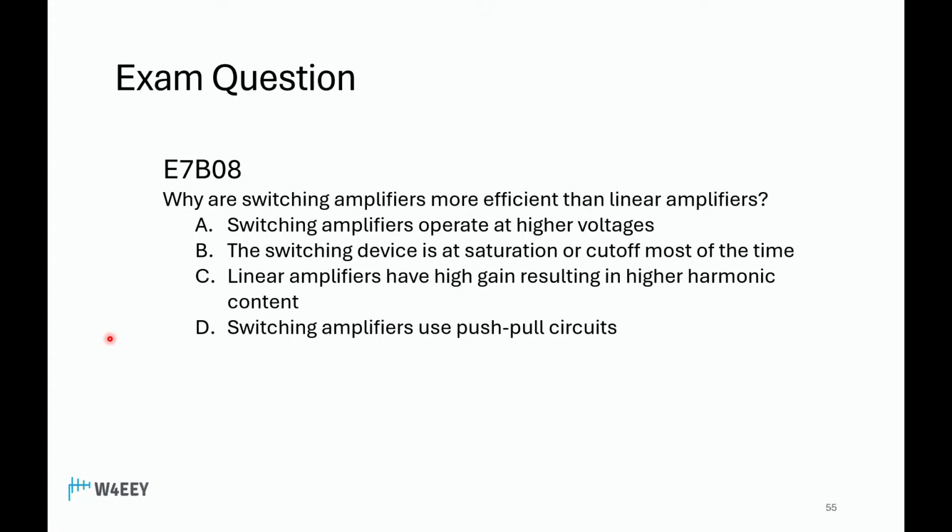Why are switching amplifiers more efficient than linear amplifiers? Delta. No. Bravo. Bravo, yeah. I don't know that I've expanded on this at all, but it is Bravo. The switching device is at saturation or cutoff most of the time, so it requires a lot less power. So it's only on a very small part of the time.